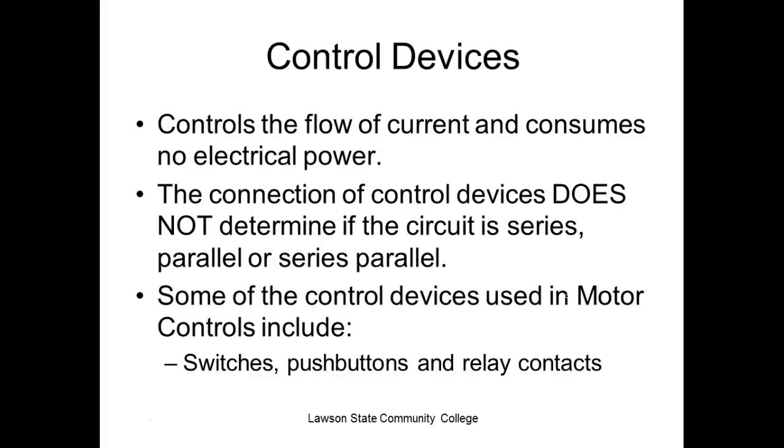So that's one thing you've got to learn right off the bat. That's got people hurt. They'll take their meter back there and measure across the switch. They measure 0 and they think the thing is not electrically hot. Then they stick their hand in there and get shocked. That's a common mistake people make.